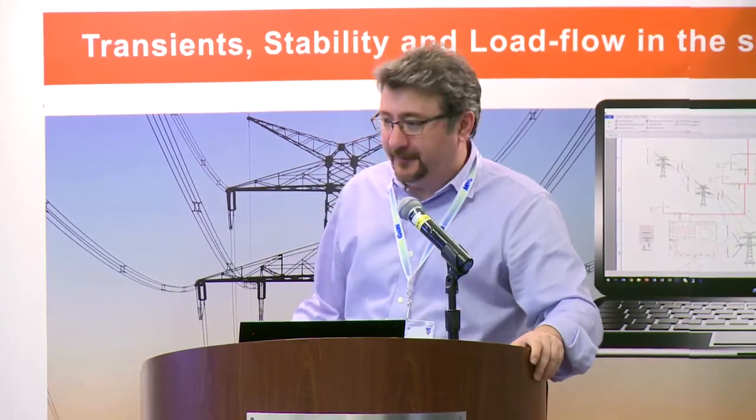In the wideband model, I do convolutions, right? Because you have a function in frequency domain, and in time domain the counterpart is a convolution. The multiplication of 2 functions in frequency domain is the convolution of 2 functions in time domain. So what is the multiplication? Your input current multiplied by the propagation function, and so on. I think he had this wrong impression, but the thing is it is 2 times, 3 times faster. It is really fast.